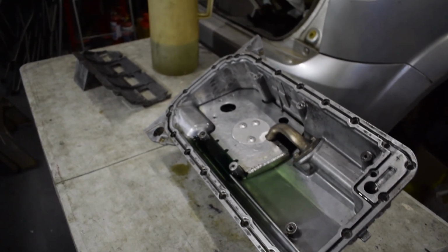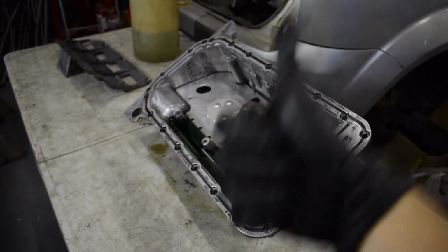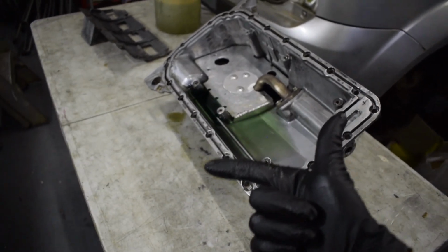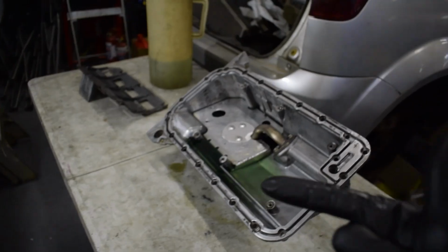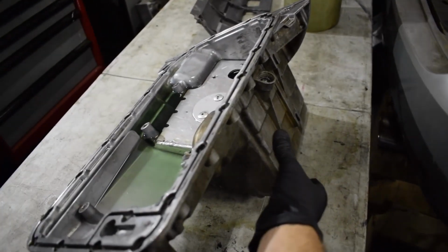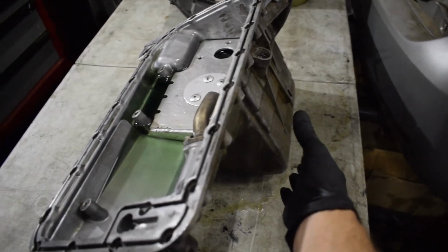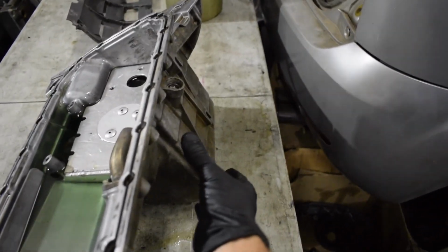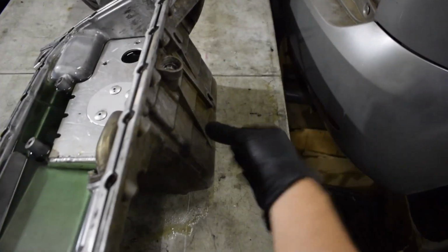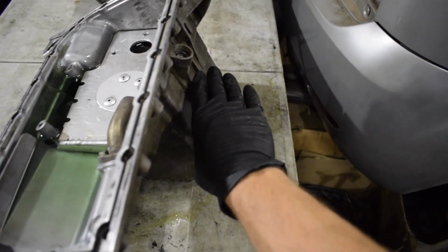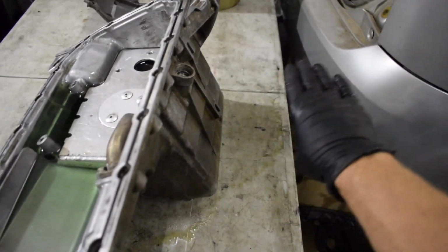How do we fix that? Well, we've got to fix two things. We need to fix volume, and we need to fix the surge. So to fix volume, we are going to box this out on the sides like you do with a lot of different sumps. So we'll basically add a box here that'll come out straight, just above the oil line.